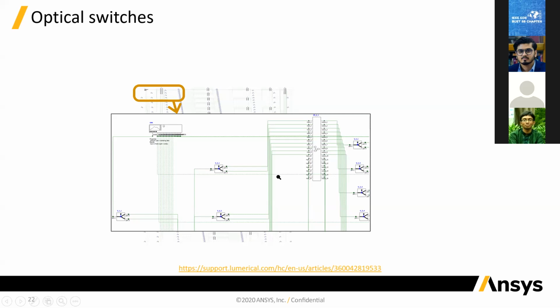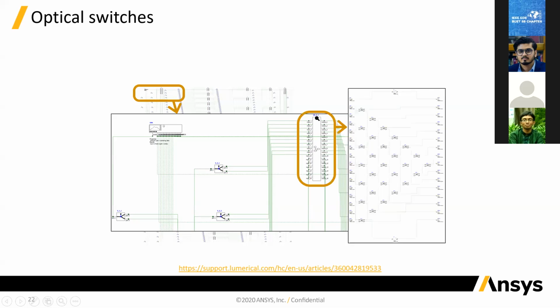And this is where the hierarchical nature of interconnect comes in, because you can create a very big circuit by cascading these different switches together, putting them inside compounds, and creating a large hierarchical network. So here, for example, you have this compound switch, which is a combination of lots of 2x2 switches connected in sequence.